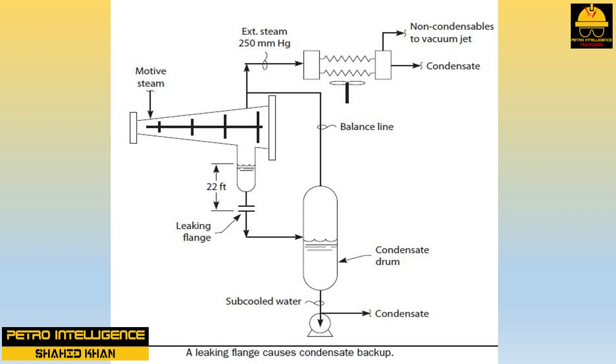If the water head pressure at the flange became less than atmospheric pressure, then air was forced into the drain line. The bubbles of air expanded as they floated up the drain line into the turbine case. This prevented the water from draining freely through the drain line into the drum. Only by raising the turbine case pressure to pressure up the flange to match atmospheric pressure could this air leak be stopped. The flange leak was taped over, and the exhaust steam pressure dropped back to 100 millimeters of mercury. The steam required to drive the turbine fell by 18%.